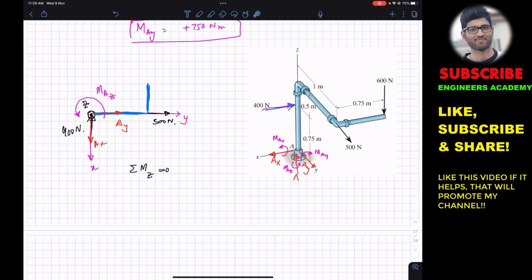But this AX, AY, and this 400 Newton force, they are intersecting with the z-axis, so they are not going to produce the moment about the z-axis. And this 500 Newton force is intersecting with the z-axis. Its perpendicular distance or its moment arm from the z-axis is 0, so it's not going to produce the moment about the z-axis.